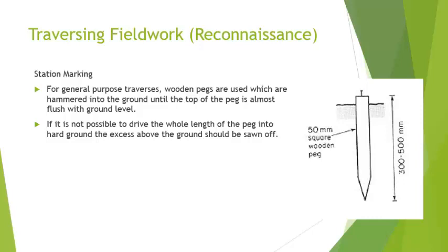But through my personal experience, working on sites where almost all the ground is hard, I came up with a method to create a guiding hole, using a metal bar which is normally used to crush concrete. I hope you know that piece of metal. It looks like a spike or a huge nail, which is used to crush the concrete.